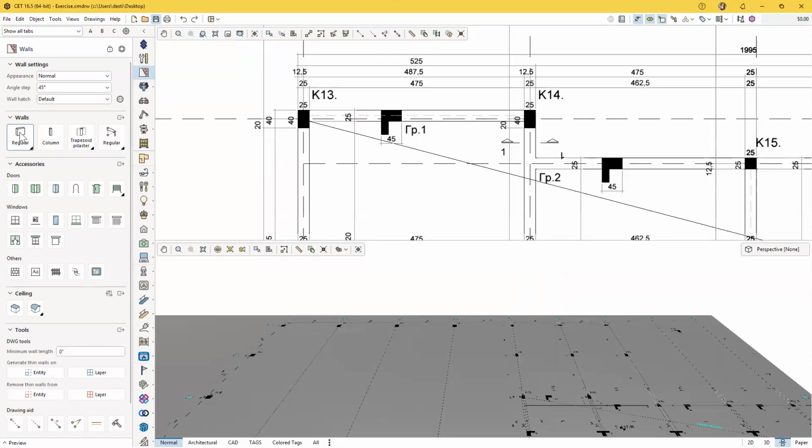When we are talking about these different types of walls, the regular wall is going to come in with the preferences that you have set for your wall schemes. A thin wall is going to be paper thin, like a poster of a wall. I recommend that you do not use these unless you really have to. They do not work well with other tools.